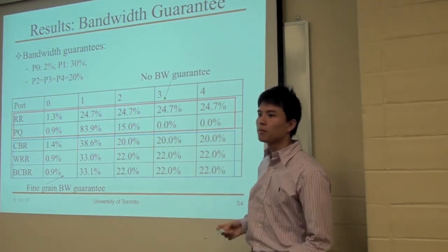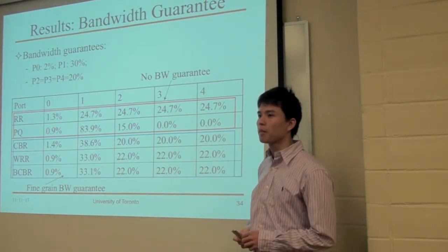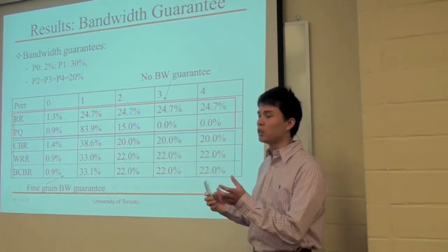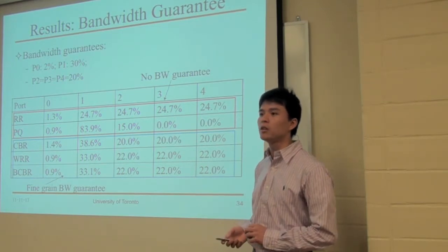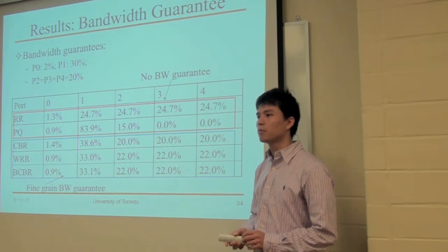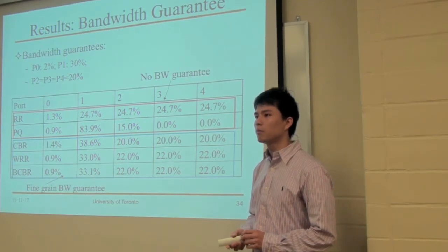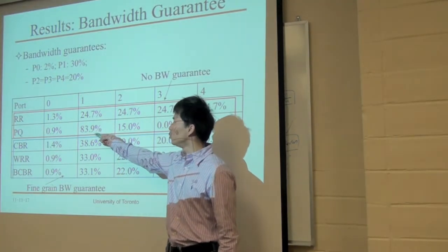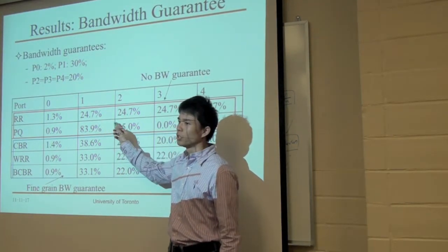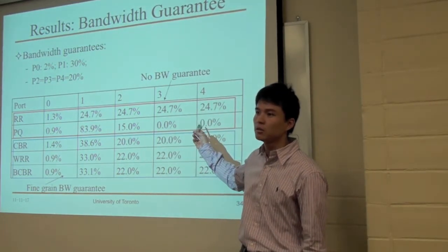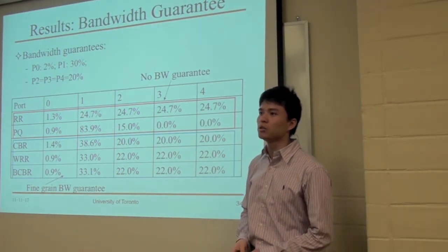And so what are those numbers showing? That in a simulation, this was what was actually used or allocated? Actually used. From the DRAM sim results. For that table, if I use a priority queue, ports 3 and 4 are not used? Yeah, if you use priority queue, because there's a request from high priority ports all the time, so these 2 ports get stopped. They get no chance to send their requests.